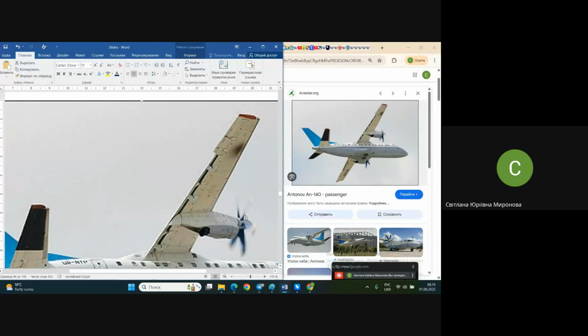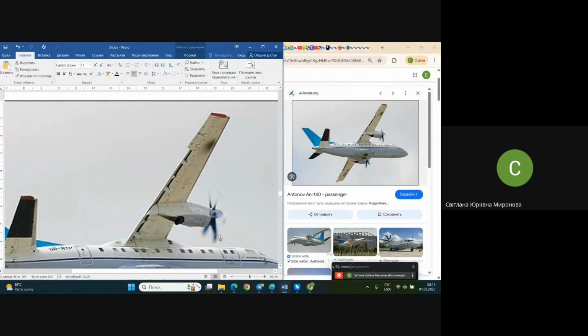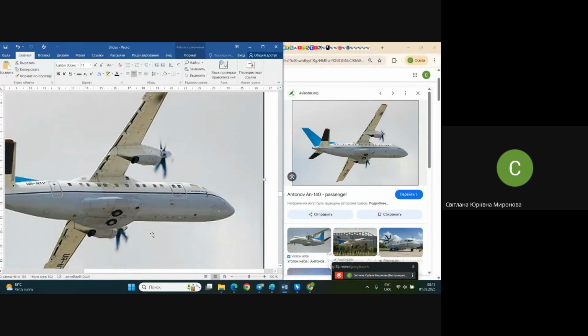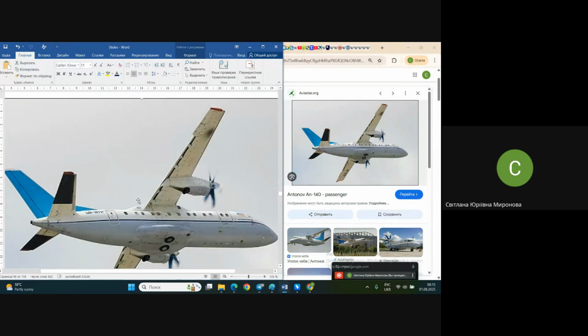Additionally, this prop creates downwash on the wing in this place. Of course, you may place it closer to the wing, but in this case maybe the downwash will be worse, and on some regimes of flight, like with flight controls retracted in the high lift position, it may result in a problem.